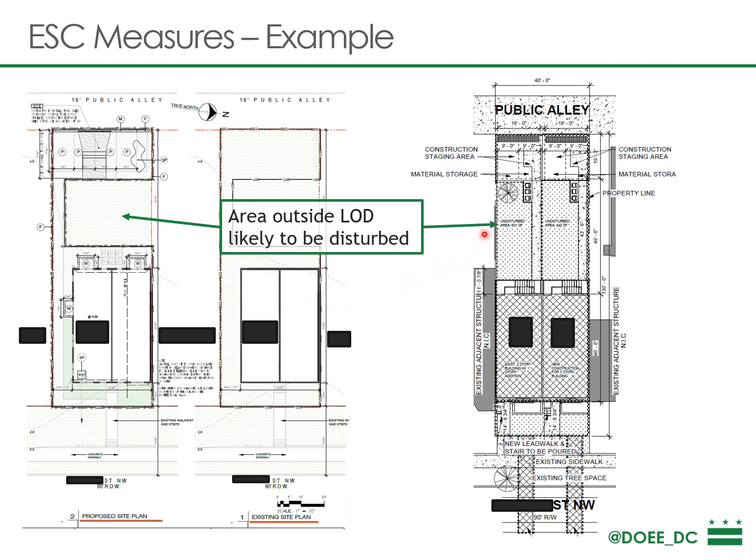Same thing on the right. Construction access is at the rear, the staging area is shown, material storage, and all of that's going to be transported through this sidewalk area without disturbing this turf area in the middle. Same thing on this adjacent lot. I think on this project on the right, what they did after a reviewer comment was they flipped one of these projects, they flipped the right side so that these two sidewalks were next to each other, and then they were able to have an 8-foot wide construction access, which was a bit more realistic for the equipment that they were going to be bringing on site.